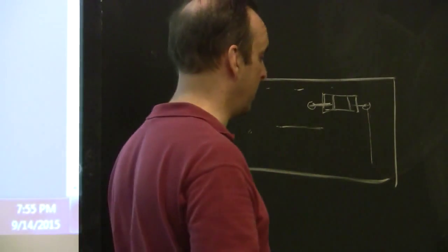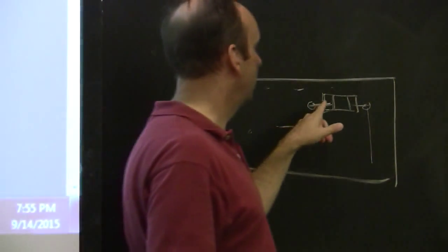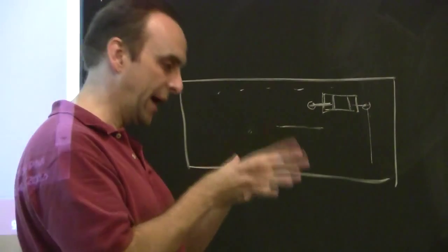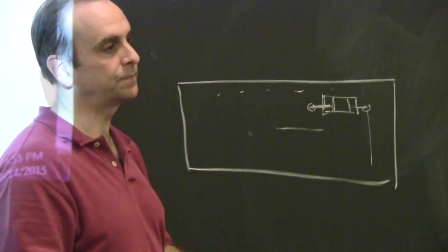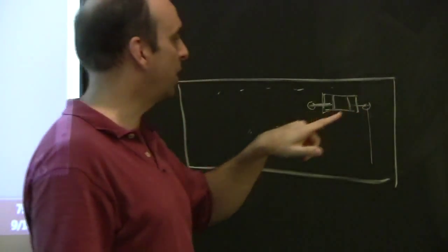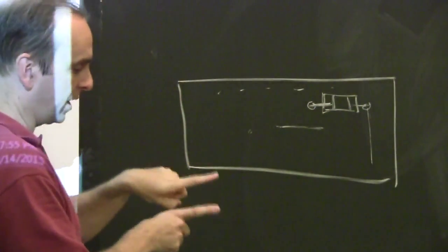There can be inductors and capacitors. Not like we're talking ideal, but the current flowing through the trace sees what it thinks is capacitance or inductance. So if you're really going to do a full circuit analysis of this device that we call a capacitor, it gets to be fairly complex. It actually looks like the capacitor.